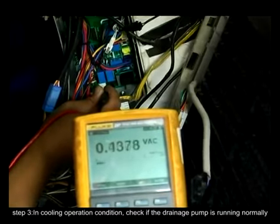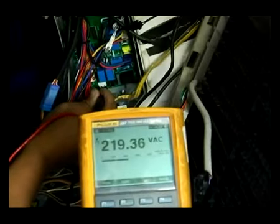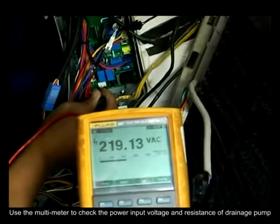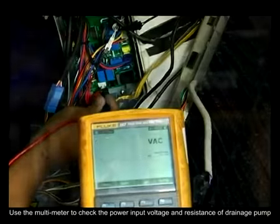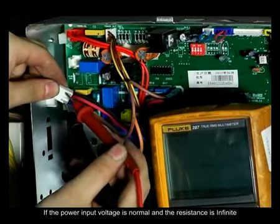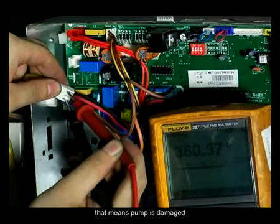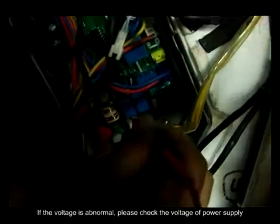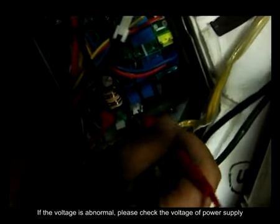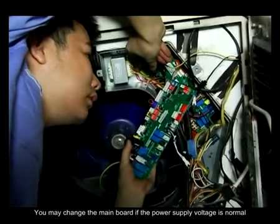Step 3. In the cooling operation condition, check if the drainage pump is running normally. Use the multimeter to check the power input voltage and resistance of the drainage pump. If the power input voltage is normal and the resistance is infinite, that means the pump is damaged. If the voltage is abnormal, please check the voltage of the power supply. You may change the main board if the power supply voltage is normal.